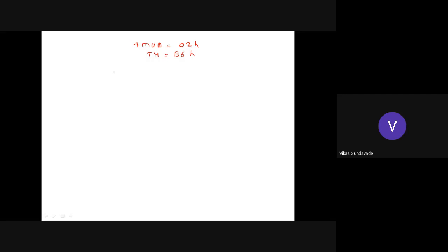So the first instruction will be ORG 0000H. Now see here, in the previous lecture I told you, whenever we are using interrupts, these interrupts have vectored locations, and these vectored locations start from 0000 onwards. After that, for every location we have different ISRs.